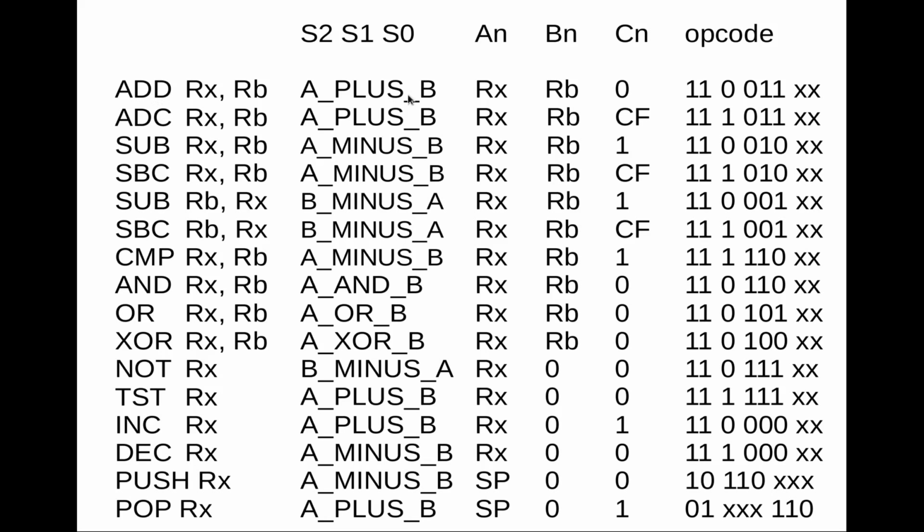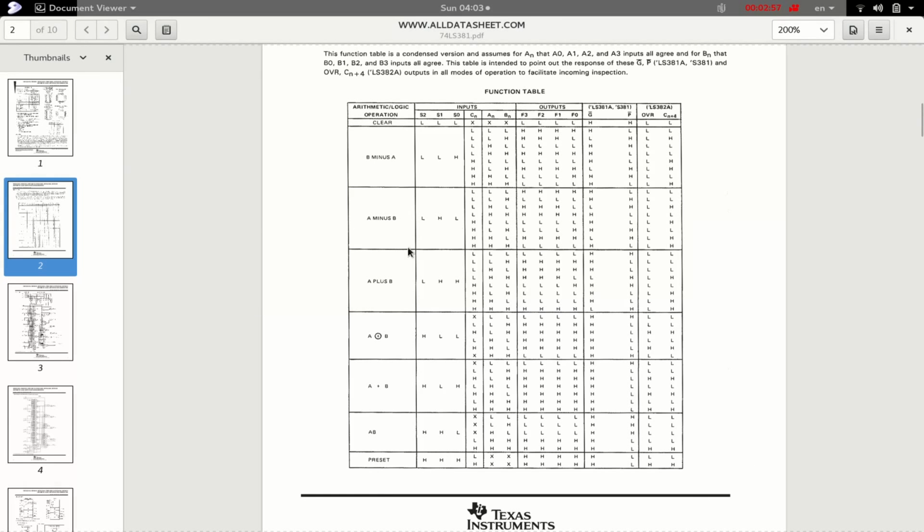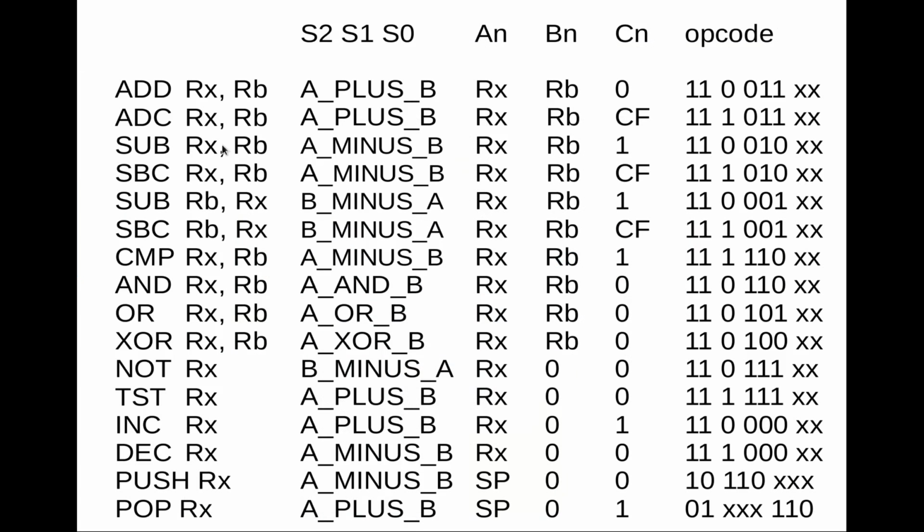And so this add will always set the carry in to 0. That won't take into account the carry output from the previous operation. But this instruction, which for the ALU is also an addition, but will actually set the carry in depending on what the carry was of the previous operation. Well, we'll encode that by setting this bit to 1. So of course that works very well for addition and subtraction. And in fact, if you'll remember, our ALU supports 2 kinds of subtraction. So we can subtract the first operand from the second operand, but we can also subtract the second operand from the first operand.